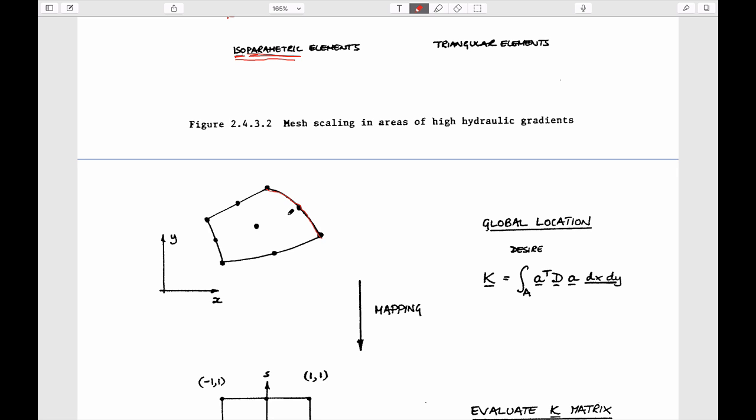And if we wanted to do that, then what we could do is use the same shape functions to map the parameters on the element as we do the geometry. And so iso really refers to the fact that we use the same function to map both the geometry and the dependent variable across the system. And we can also define other cases as subparametric elements, where we use a lower order shape function.